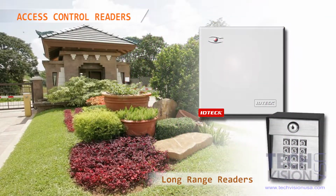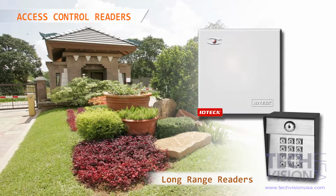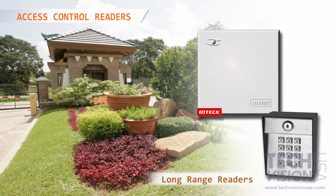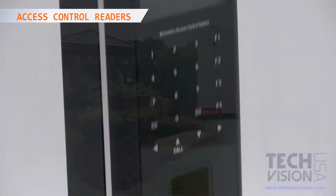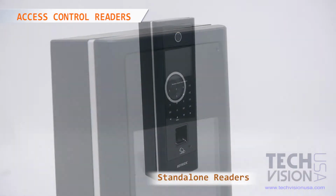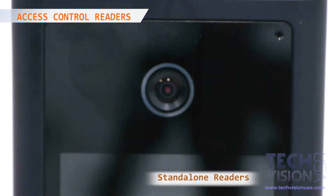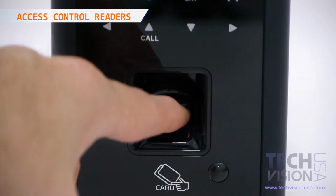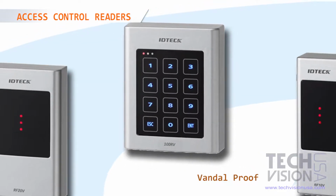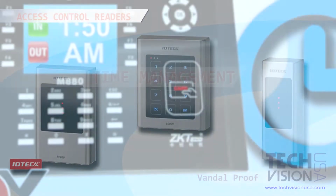Long-range readers. These types of readers are typically used for outdoor applications, such as vehicle access. They are capable of detecting a long-range access card at much further distances than proximity readers. Access control standalone readers. Many readers are required to be connected to an access control board to utilize software in order to function. Standalone readers are just that: hardware, software, and controller all in one unit. Many readers also come in a vandal-proof version. Vandal-proof models are resistant to vandalism and are usually weatherproof.